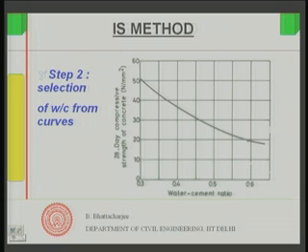First curve would look like this: water cement ratio versus 28 days compressive strength of concrete. So, there is a single curve, and this represents a single curve for all concretes made with all kinds of Indian cements, basically based on empirical experimental data that was generated by doing a lot of tests early in the 70s, and from that the water cement ratio versus strength curve was determined.